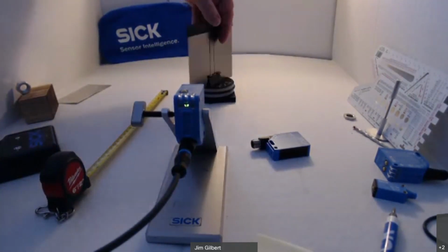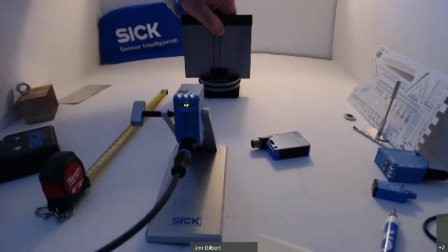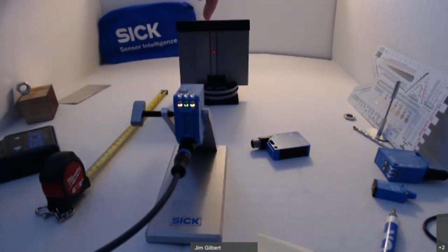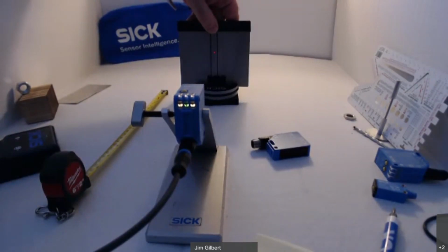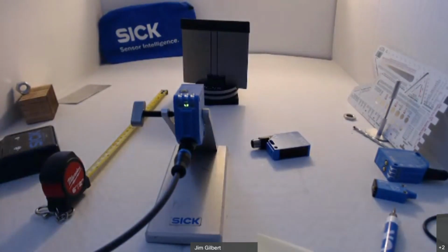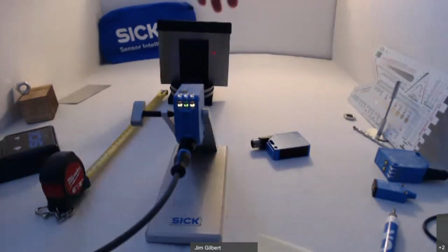Now, if you move to something that has a shiny surface, that can be more difficult. In this case, I'm going to use the same teach point that I had before, except now I have an aluminum surface. This is a paint scraper I got from the hardware store. As I rotate this, you'll see that it won't be able to resolve quite as far. I'm looking for when it turns, and I'm looking at my detection angle, and that is a detection angle of maybe close to 25 degrees. So you can see the big difference between a matte black surface and something that is shiny. There is a big difference.